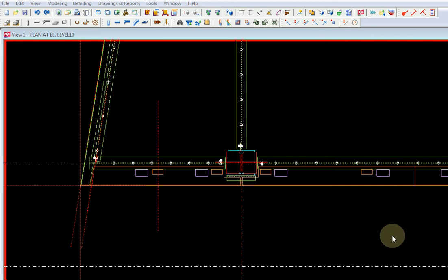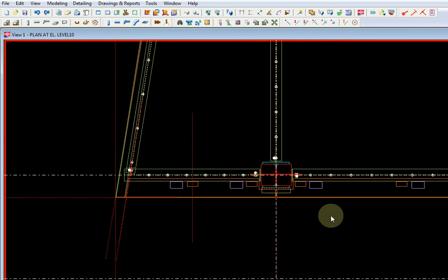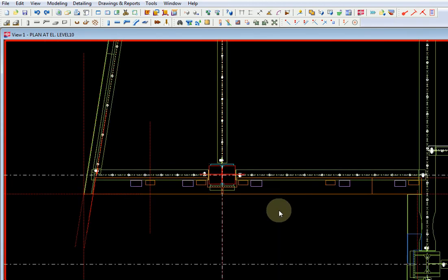Use auto connection in Tekla Structures. Auto connection is the most effective way to do the connection, but unfortunately in most jobs it's not possible to use it because they have a different type of connection, and you have to use a different way. Also the input is another issue. If there is no input, or every input could be a default value, you can use the auto connection. Otherwise, you cannot do it.